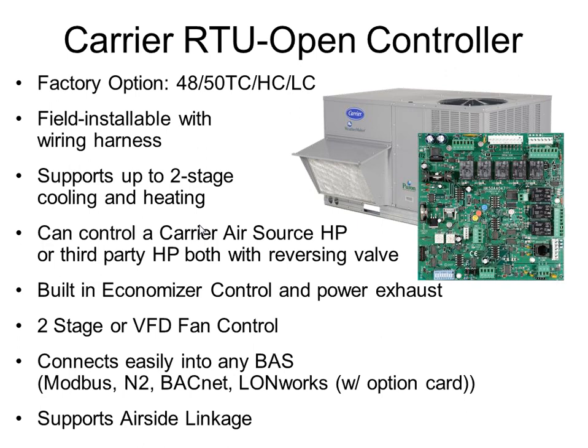It can control 2 stages heat-cool, economizer. It can actually do the 2-stage or VFD fan control now, and these are actually able to connect to other BAS systems, Modbus, BACnet, LAN. It is a native BACnet controller, but this would be the controller that we would include on any Carrier VVT system. And one of the big proponents of why is because it supports what Carrier calls airside linkage.